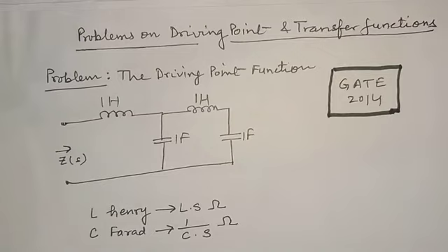In this lecture, I have considered problem on driving point and transfer functions. One question I have considered in which driving point function is to be calculated. Driving point function is actually a network function where measurement of voltage and current are considered at the same point or same port.